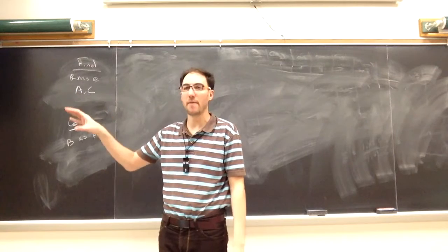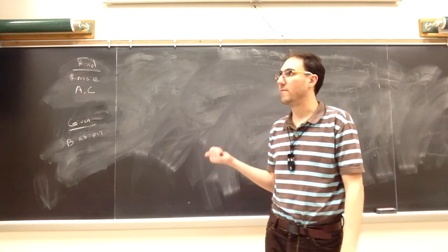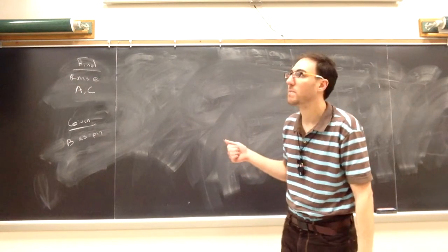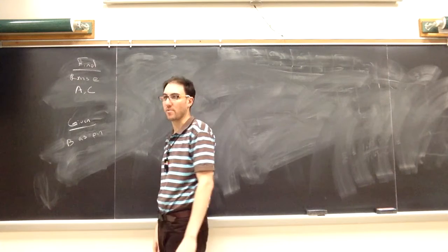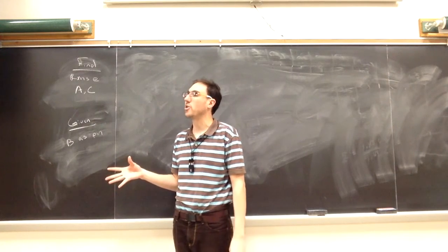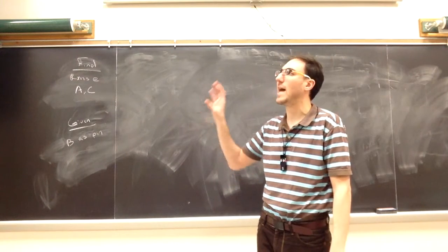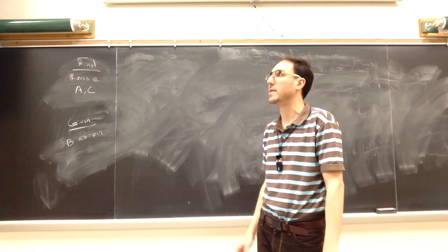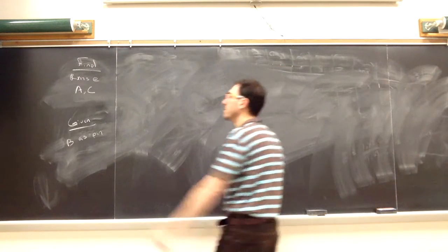We'll have 3 reactions at the wall at A: a force in the Y, a force in the X, and a couple. And then we'll have a 4th reaction at C, just a force in that Y direction. So it's statically indeterminate externally. It's a frames and machines problem, and in addition, we see a distributed load acting on it that we're going to have to account for when we're solving this problem.